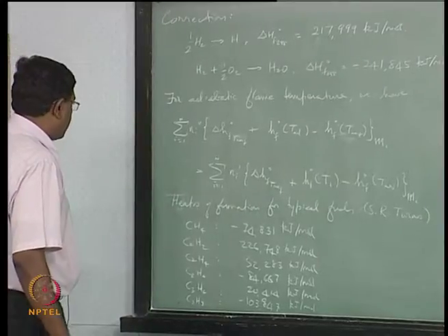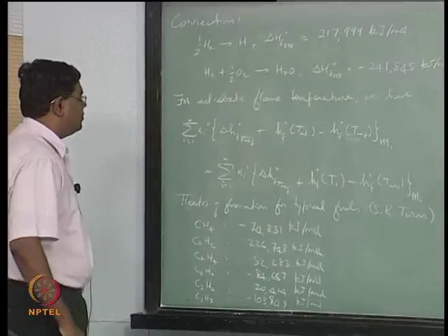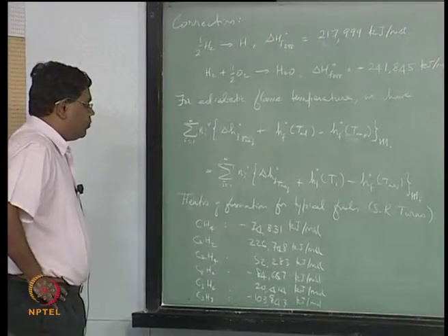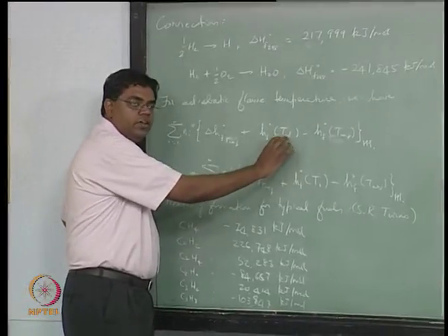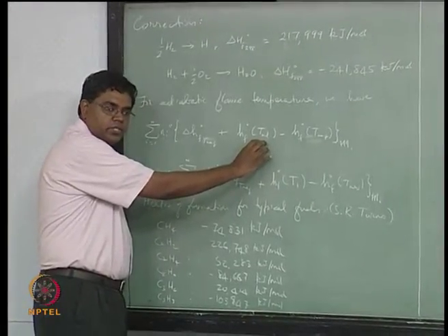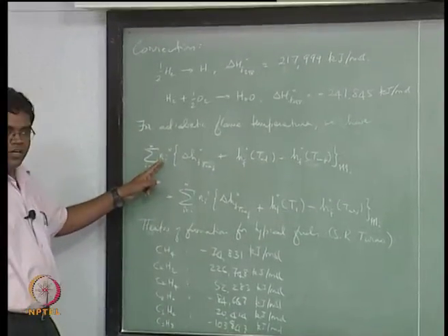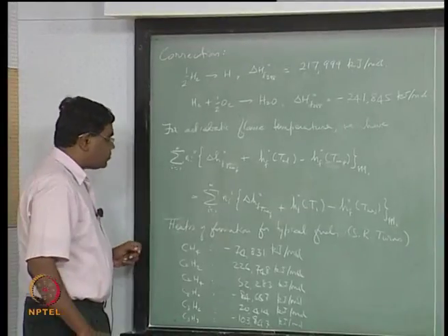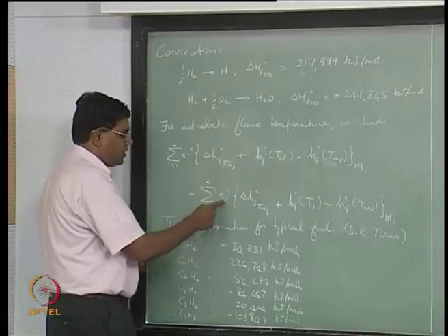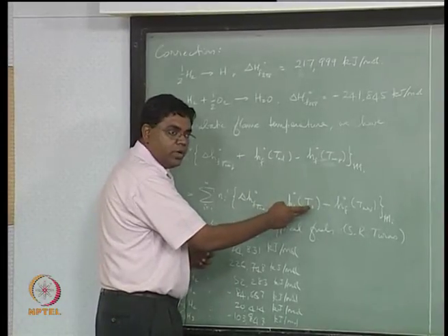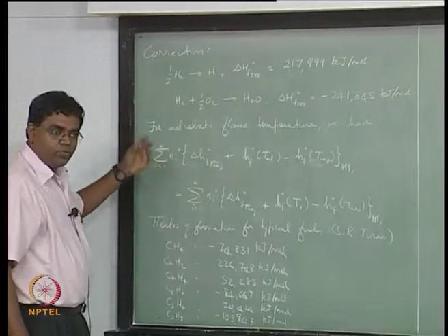Okay, so we were talking about this equation that's used to find the adiabatic flame temperature, and the point I was trying to make there is, if you want to have a fairly high adiabatic flame temperature for the products, which is given by having this Ni double prime over here, then what's given to us is Ni single prime and T1 and maybe the pressure, which will determine Ni double prime in a way that we will see.